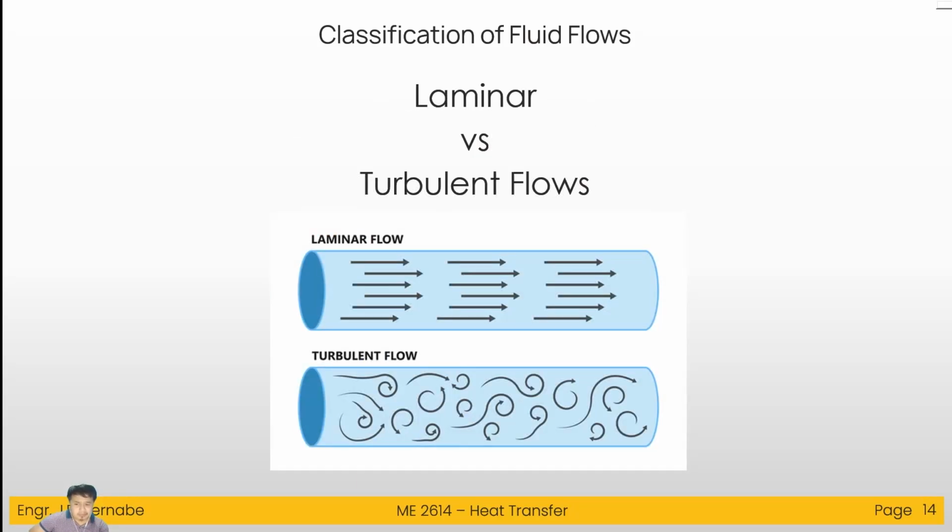Okay. So for laminar and turbulent flow, we have two different flows. For laminar, you can imagine laminar flow as the flow of honey, and turbulent flow might be the flow within the pipes of your home. It's turbulent. So you can imagine laminar flow to be consistent with low velocities. If it is low velocity, it is a much smoother, cleaner flow. So if it is honey, for example, it should be high viscosity. So low velocity, high viscosity. If it is highly viscous, it will be laminar for most of its range. But for less viscous and high velocity fluid, it will experience more turbulent flows.